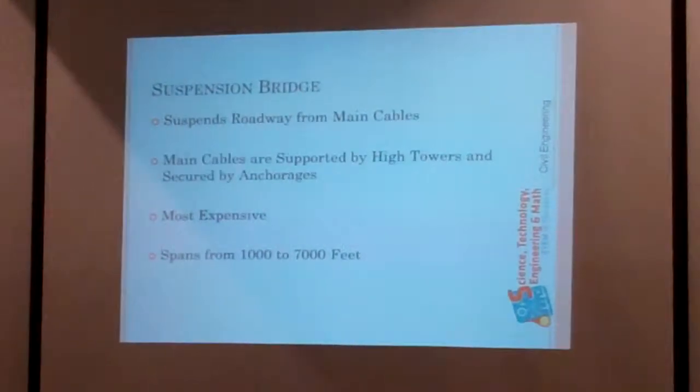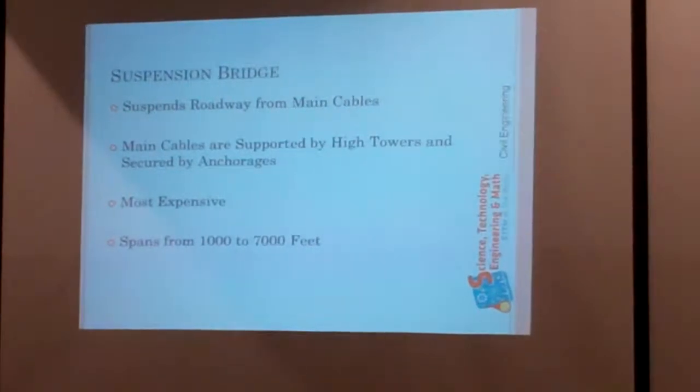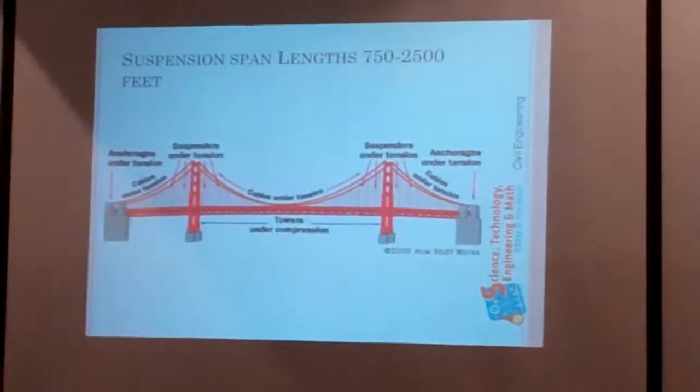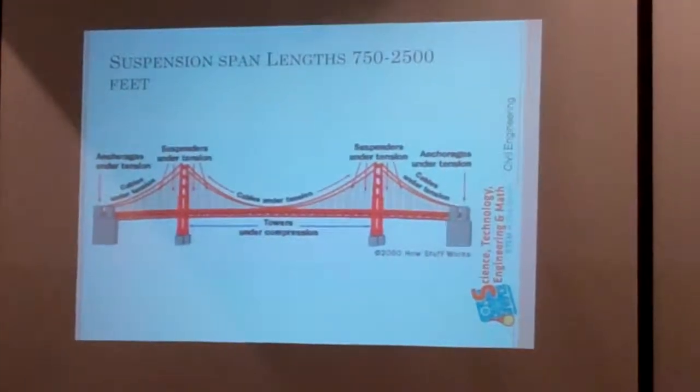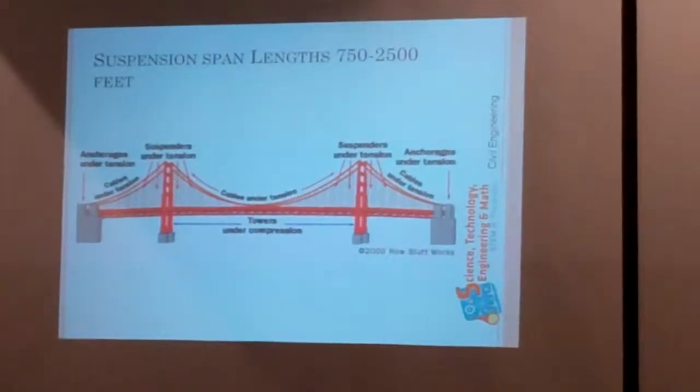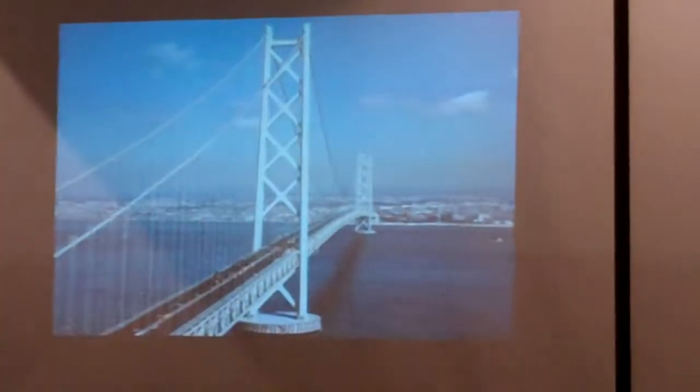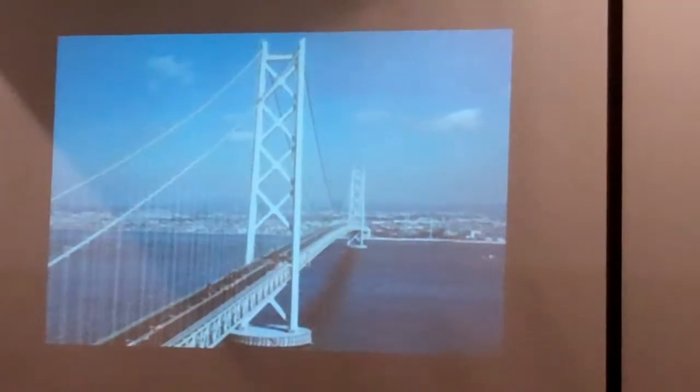Suspension bridges. Suspension bridges are built for very long spans. They're very expensive, but when you don't have space to put center piers in the water, they serve their purpose. It's to create long spans, and so the force here is you have two vertical towers. Cables are draped across those, and the load is transferred through the cables, through the tall towers, and then to anchors into the pin. These are like the bridges you see, like the Golden Gate Bridge. These are called suspension bridges. They're very expensive, but they do serve their purpose to create a very, very long span.